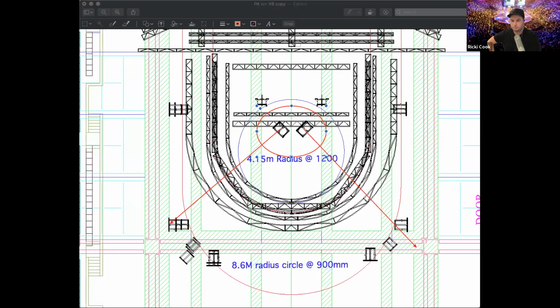Yep. Number 2 from me would be the PA should always sound good with a vocal mic. With the PA flat, you should be able to talk into a vocal mic and it should be clearly audible. If the vocal mic sounds muffled, then I would be suggesting you modify the EQ on that PA system.